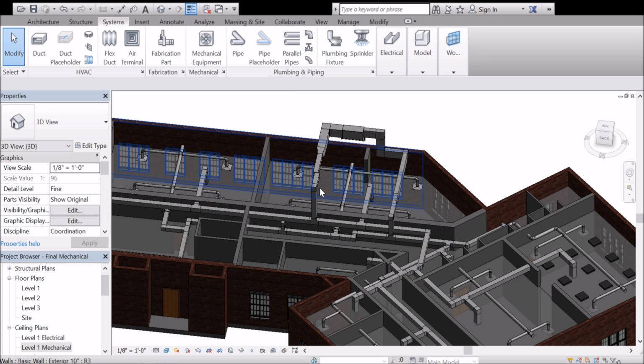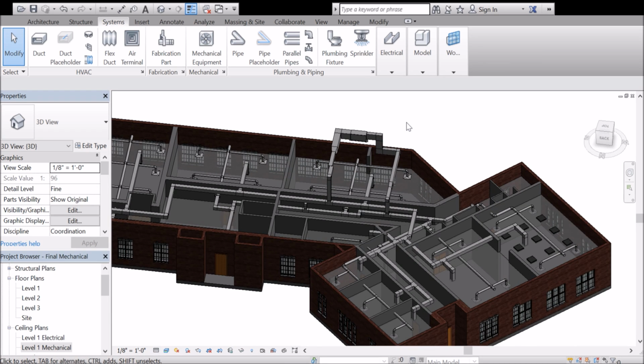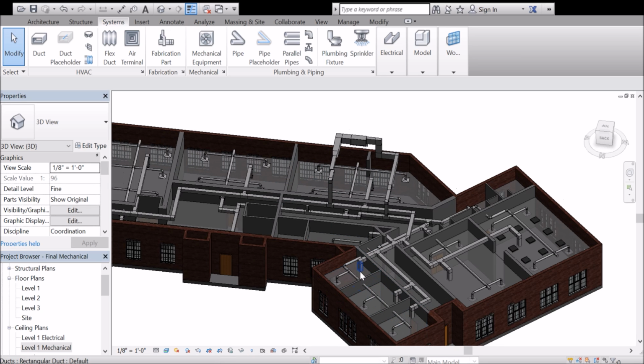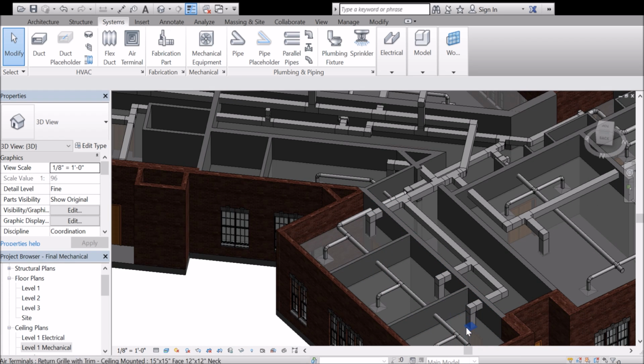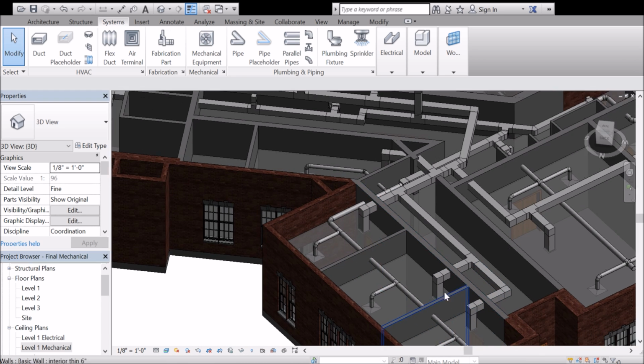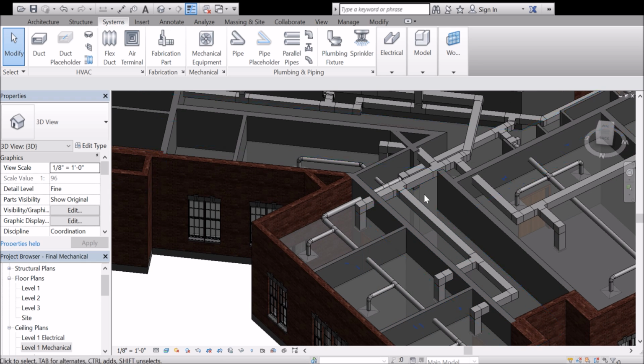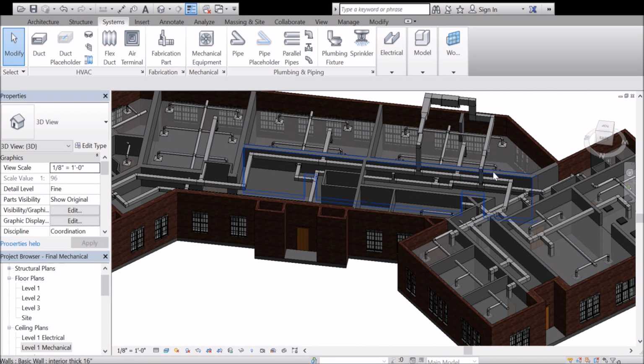So once you have that, you're going to duct in to your air handler. And the last thing you have to do is duct all your returns. And the process does not change at all for that. It's basically the exact same as your supply lines, except there's no VAV box now, and we're using square ducts. So go ahead and just draw square ductwork connecting all of your returns. If we look at these three rooms, you can see I have square ductwork coming out of all of them, and it's just combining everything as we go. So we're combining all of these into one centralized line, just like we did on the supply line.